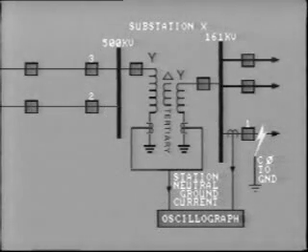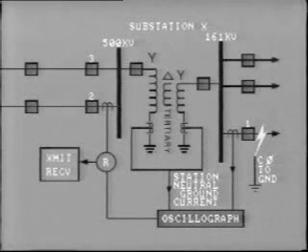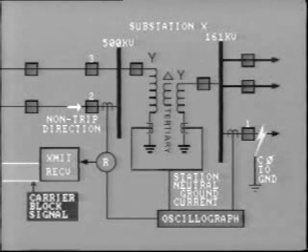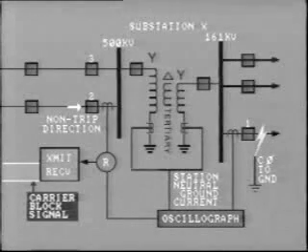In this particular incident, the relays associated with breakers 2 and 3 on the 500 kV system registered the high current, but decided that the fault was in the non-trip direction. Carrier block signals were then sent to block tripping of the remote breakers. This is correct.